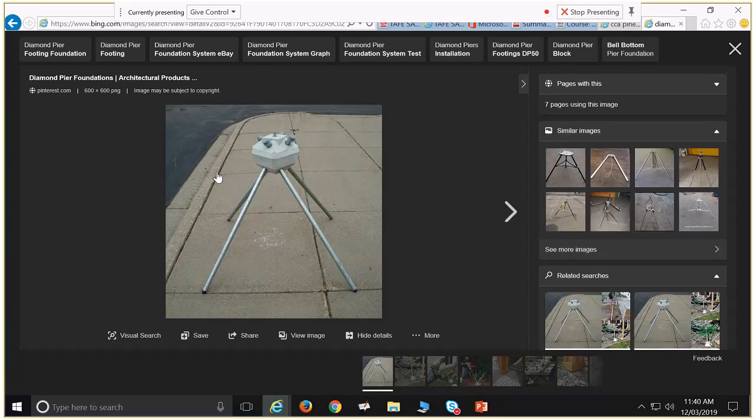What it is, well, once again, it is a bit of concrete, right? But it's not a lot of concrete. So you've got this little concrete thing which is precast, and it has holes which are heading in a direction, and then you can get sections of galv pipe with a post rammer and just drive those in at these defined angles, fix them and lock them.